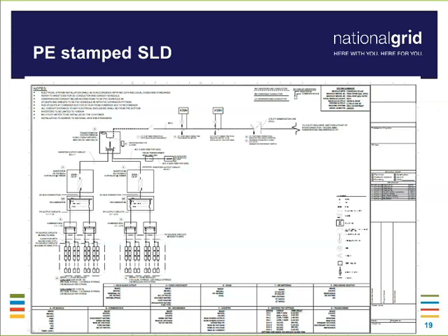The most simplistic fashion of showing that would be to list the conductors. For instance, if it was an overhead line using a 336 type ACSR or an all aluminum or whatever the conductor type would be, you would list out the conductor type on the drawing. And lengths would not necessarily be needed on a single line if they were covered on the plan view or some schedule, but lengths could also sometimes provide assistance to us.